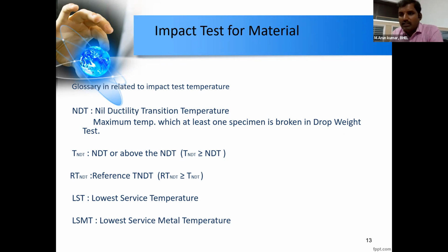I want to emphasize that this affects the performance of our equipment, which is designed for nuclear application. Then we did many root cause analyses, and we could find that the heating and cooling rate in the heat treatment cycle influences the ductility of the material.